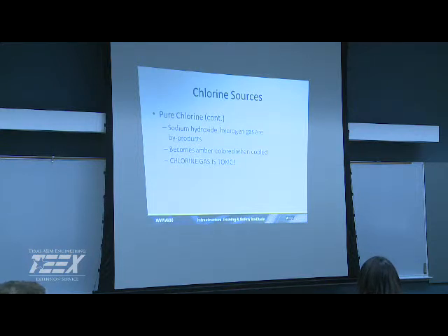And one of the big things when we were talking yesterday was about people doing changeovers. They were using 150-pound cylinders, and I asked them, "Well, do you have your respirator stuff?" They said, "Well, we have them." Okay, that doesn't mean you're wearing them. That means you have them. It doesn't do you any good if it's hanging on the wall, sitting in a closet, or sitting in your locker. It's not to go in and do repairs, but it's an escape mechanism.